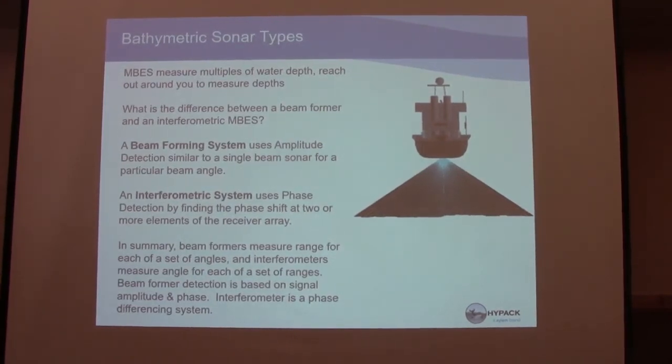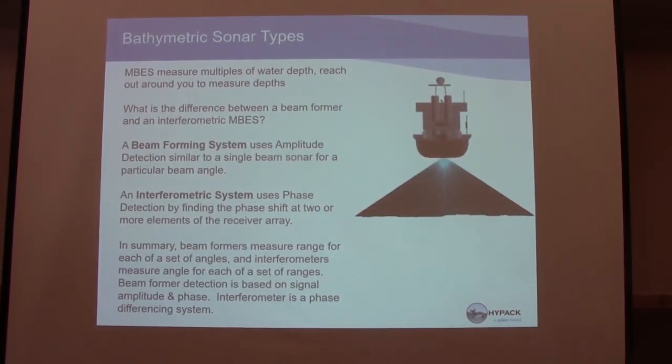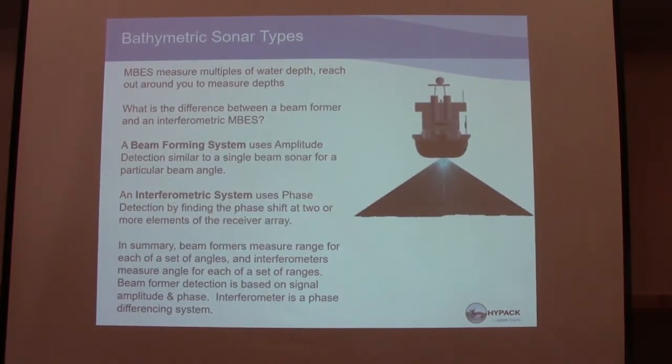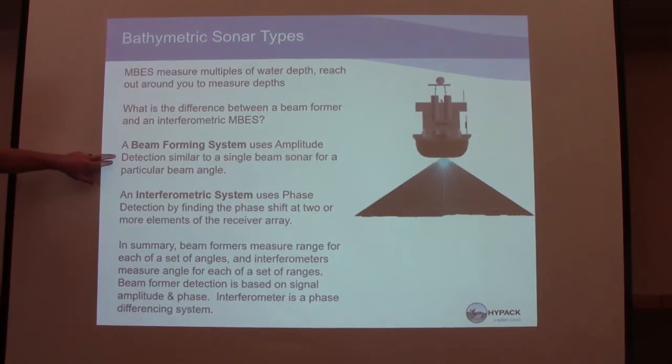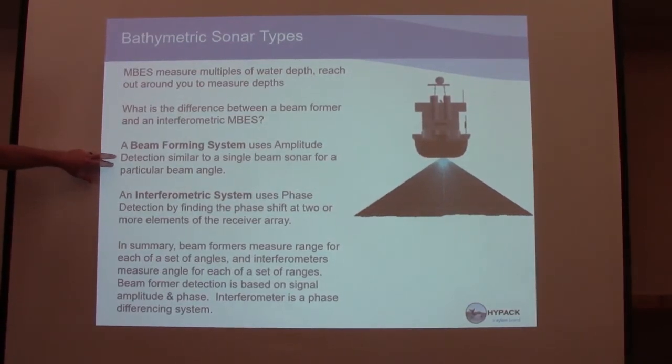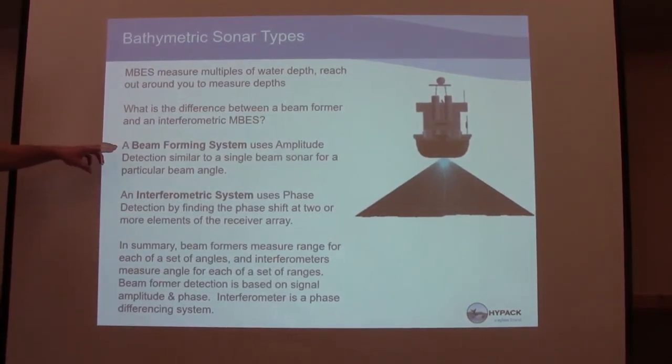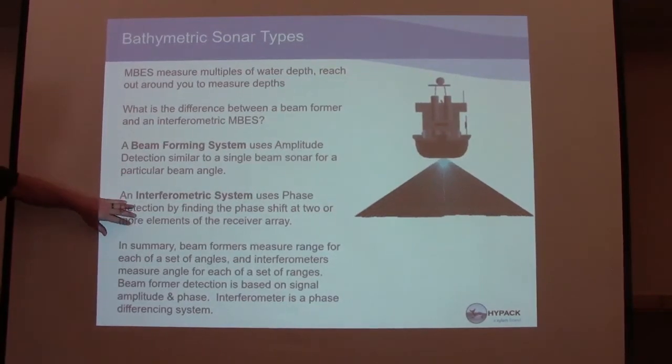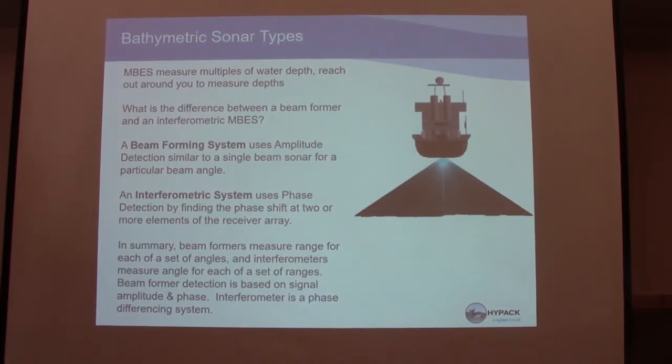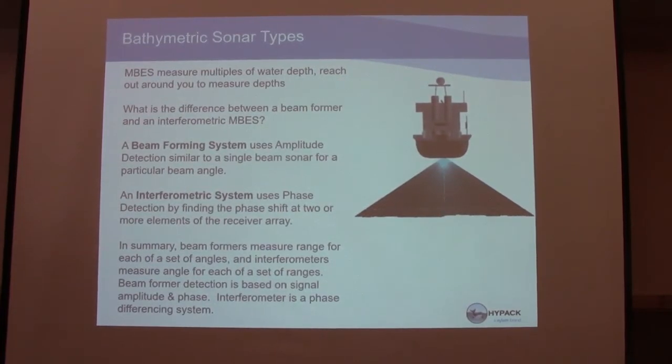Does it pass IHO standards or USACE hard or soft bottom standards? I don't know. You have to do a performance test on that stuff. But both are really nice. Odom and Norbit have beam forming systems. Down here with interferometric systems, you're talking about something like an EdgeTech 6205 or an OEM 2205. Just slightly different technology on how it digitizes the depth.